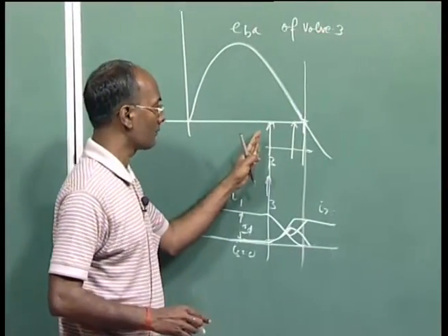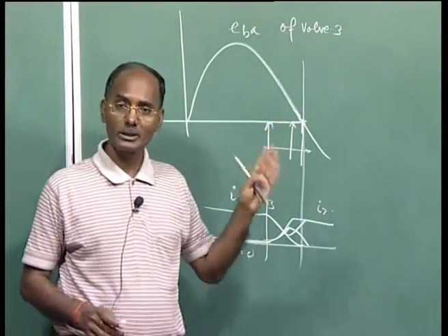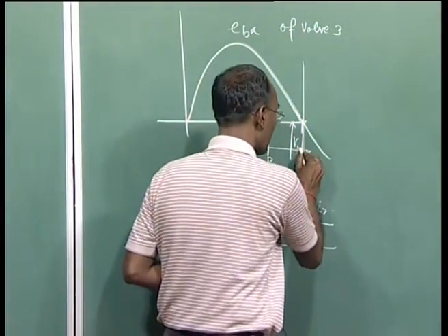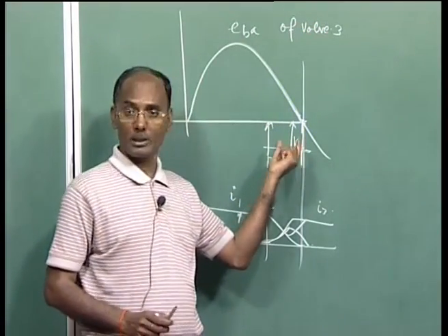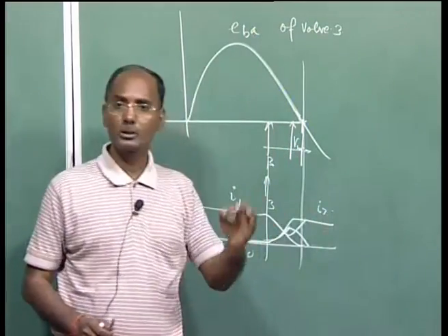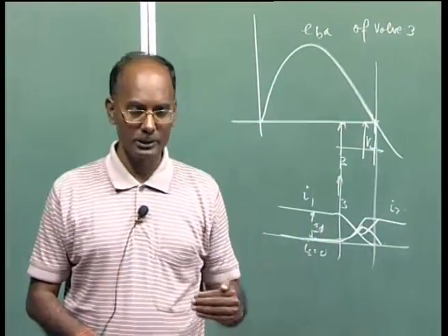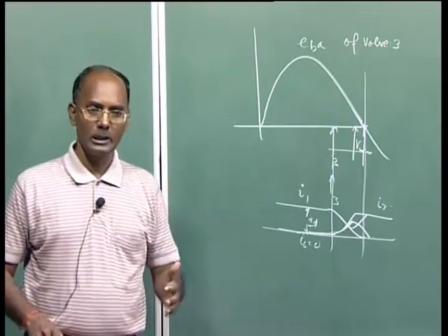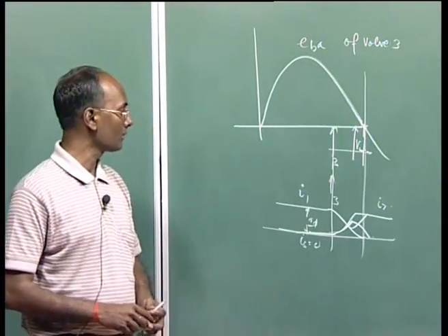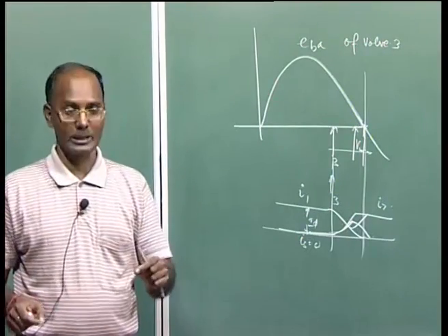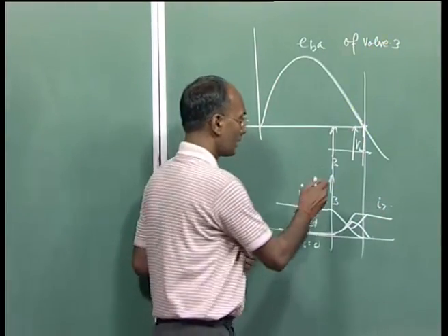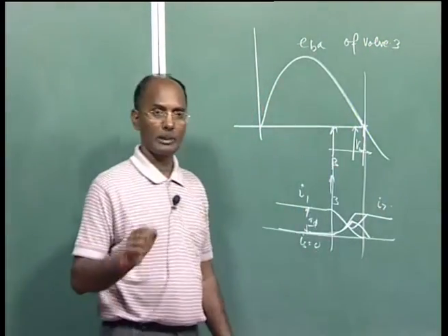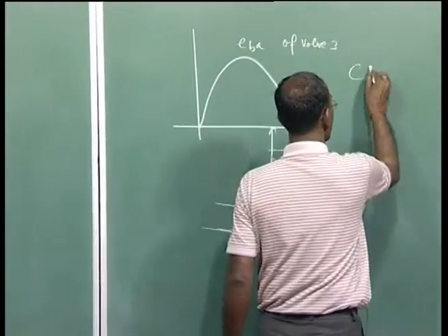Now the major cause for this: on the inverter side we use the CEA control, the constant extinction angle control, where we maintain a minimum gamma of 10 degrees, not 5 degrees, because we keep a larger margin. We want to be sure there is no commutation failure, because its impact gives you reduced voltage, injects harmonics into the system, and causes a DC short circuit across the inverter circuit, which we do not want. So here the beta is calculated; I already explained how the constant extinction angle control works.